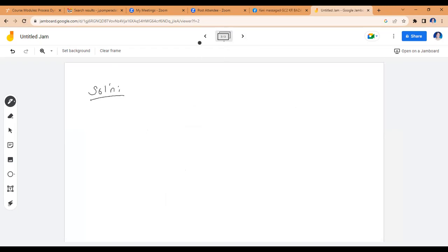Now we need to establish the Peclet number, so we will know the correct formula to use for the Nusselt number in this case. Your Peclet number is the Reynolds number and the Prandtl number multiplied. So if this is our equation 1, we'll have it labeled there. Now we'll determine the Reynolds number. The Reynolds number is the mass velocity G times the diameter of the pipe divided by the viscosity. So this is the mass velocity, this is the diameter of the pipe, and this one is the viscosity.